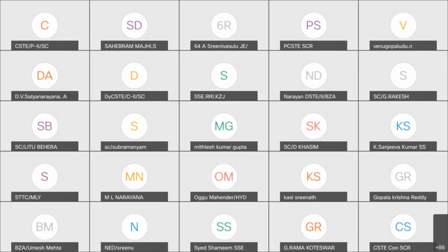Now we are converting, sir, to series track circuits. Yes, we sanctioned the work last year, and in fact, from here I want to say to everybody, all senior DSTs, all supervisors, that please communicate if there are parallel connections in track circuits in your stations. Please communicate immediately to your senior DST so that a consolidated work can be sanctioned and executed. All can be converted into the series one. It is an unsafe situation that should not be allowed.